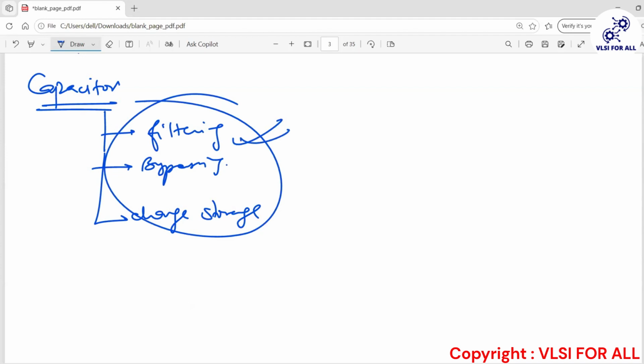Now there are different types of capacitors in the PDK. There can be metal insulator, metal oxide or metal to metal, high precision, PN junction capacitance, and poly to poly capacitors. All these capacitors are present in the PDKs, because whatever you want to use, you need to take it from the PDK only. You might create your own, but that will not match with the foundries. So that is one thing. Now again, it depends on what type of capacitors you are using.